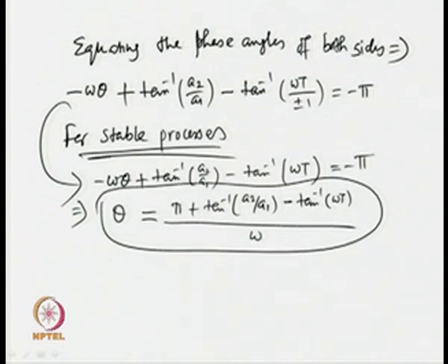So, the explicit expression for the time delay or theta associated with the transfer function model is obtained in this form. Now, again I am telling, the measurements we make use of to obtain or estimate theta are omega, and the measurements you have for A1 and A2, and t has been already estimated earlier. So, I can use t in this expression.